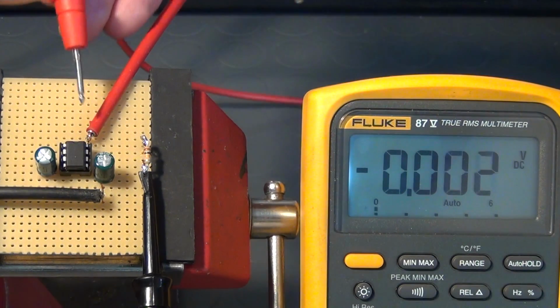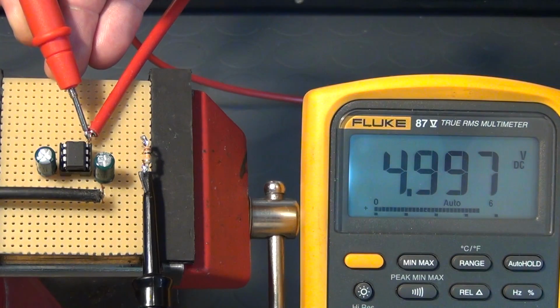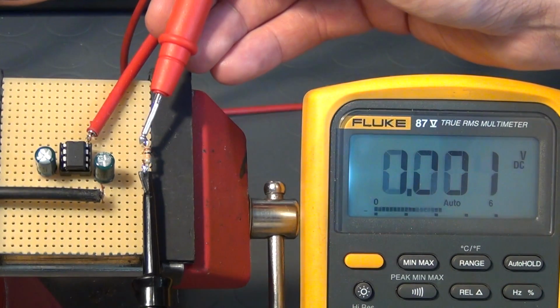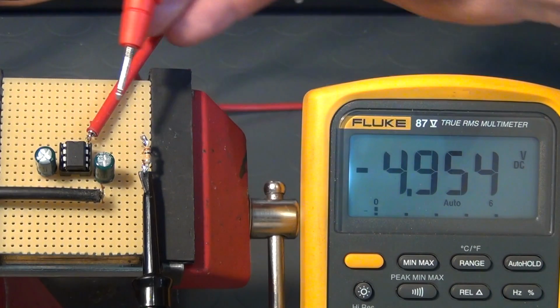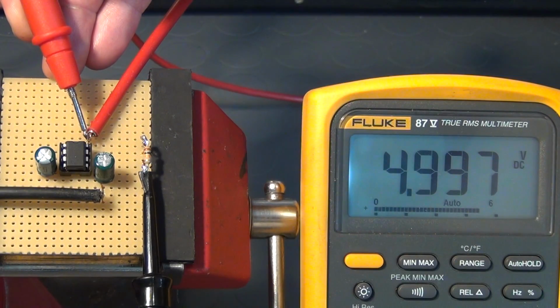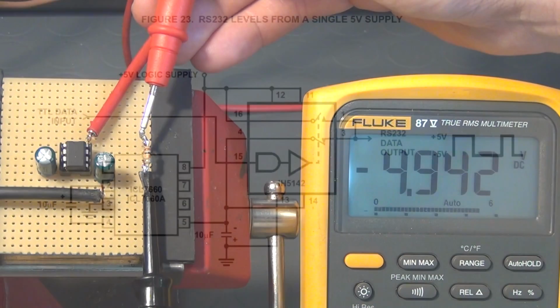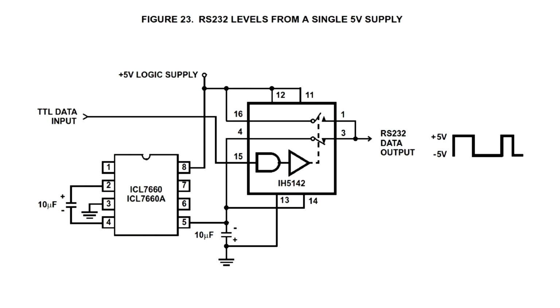You ask what that would be good for? Well, it allows you to power certain devices which need two symmetrical voltages from a single rail power supply or a battery. Typical applications are therefore RS-232 interfaces and other digital devices like dynamic RAM or 8080 microprocessors.